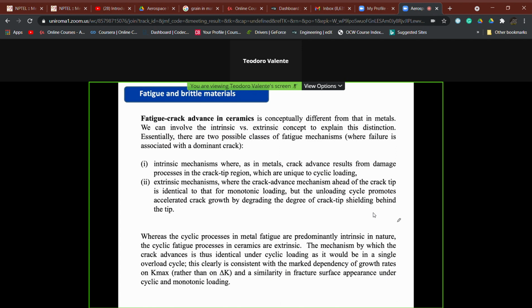But as I told you last time, when we some years ago started to discuss fatigue, we were limited in our approach only to the use of the Paris law. This is the reason we have now made some additional considerations, in order to let you know also other models, including the NASA one, which can be used for fatigue prediction of metallic alloys.